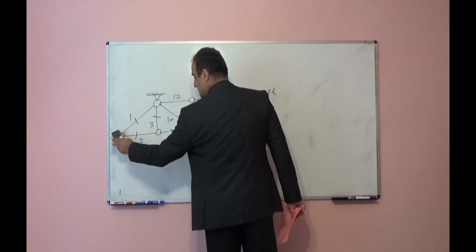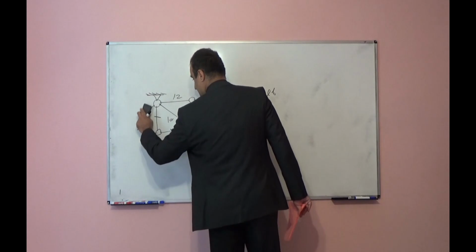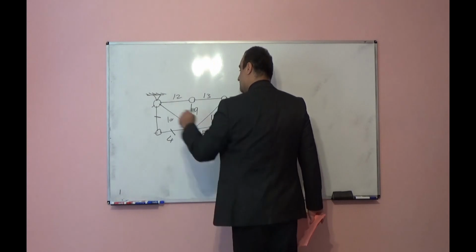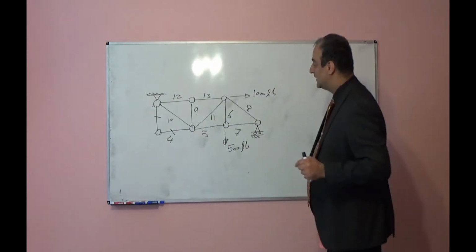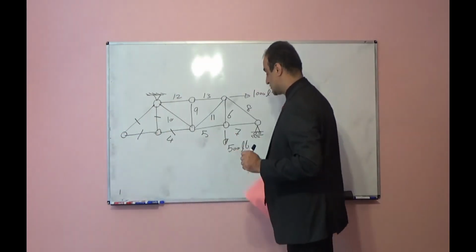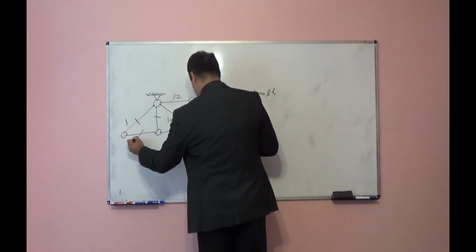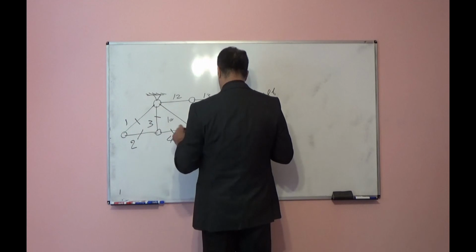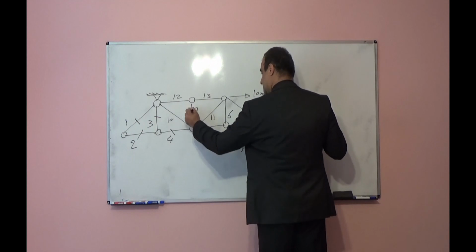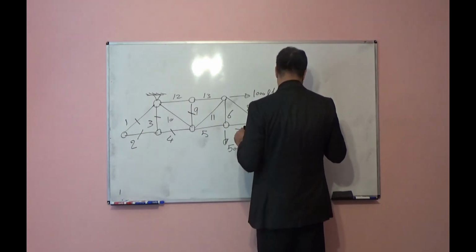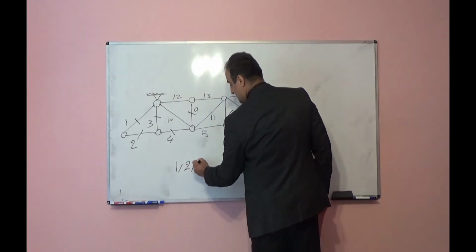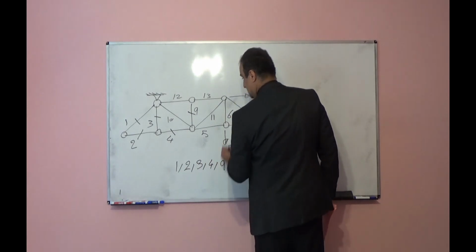If you remove those, even here, both of them come to the joint, there is no external load, both 0. So let's move to the next one. So, member 1 is 0, member 2 is 0, members 3, 4, 0. This joint, 2 of them collinear, there is no external load, this is 0. So, 9 is 0. So let's look at 1, 2, 3, 4, 9.